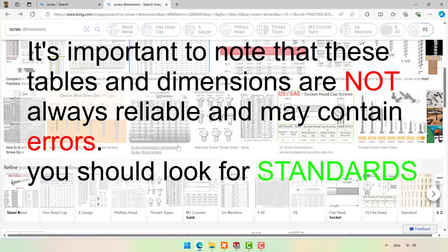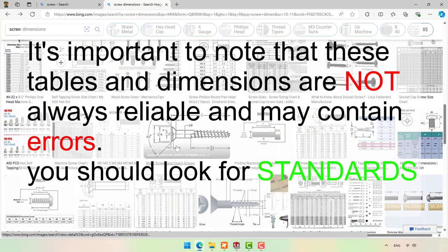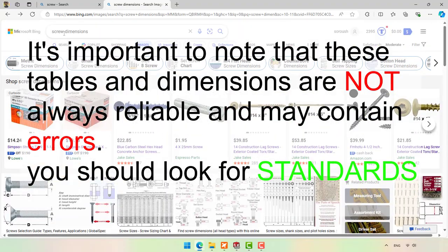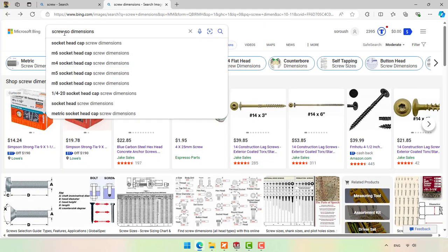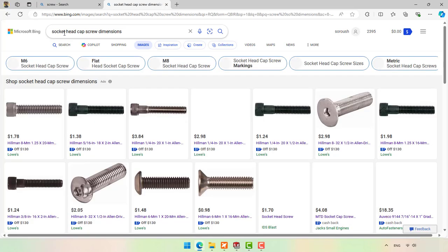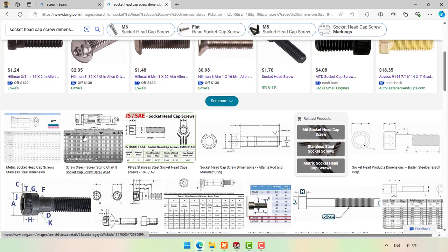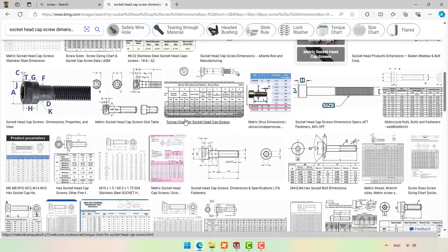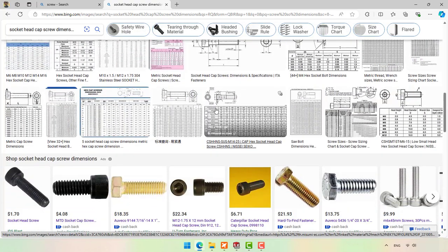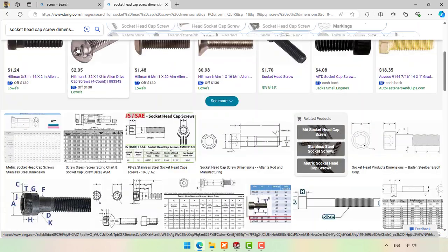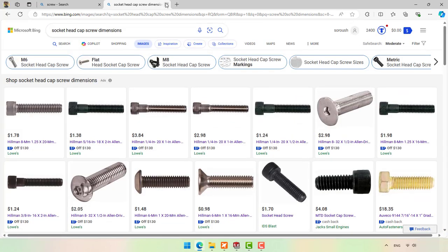First of all, let's look at the dimensions of the screw. For example, we are going to design a Hexagon socket head cap screw M20. We'll need to know the thread length, diameter, chamfer size, pitch, and other dimensions of the screw. How do we find a reference for these numbers? Thanks to organizations like ISO and DIN for setting standards. The best way to get these dimensions is by using pre-published standards.